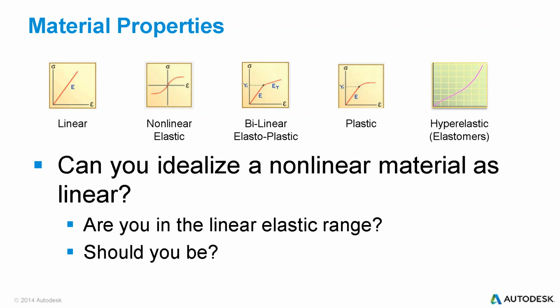So one question we get a lot is, why do I need to use Nastran versus what Inventor already has built in inside of Inventor Pro? Well, there are limitations in Inventor Pro, one of which is it's linear only. It cannot work with any type of nonlinear materials or nonlinear calculations. Also, it's static only. That's the limitations for Inventor Pro.